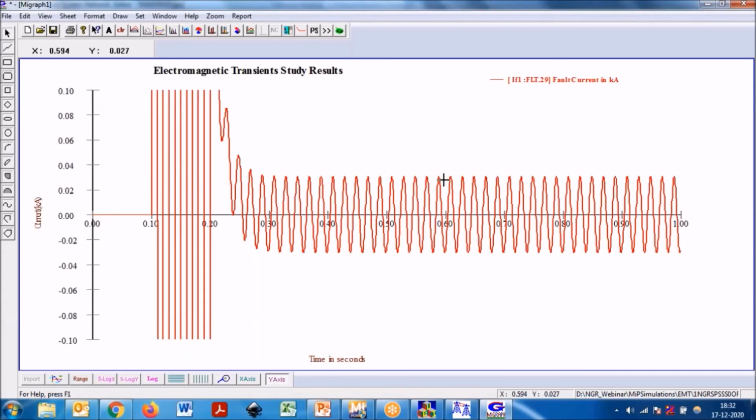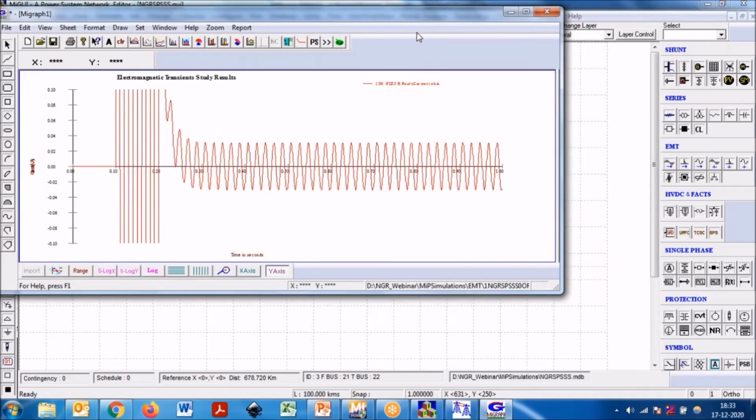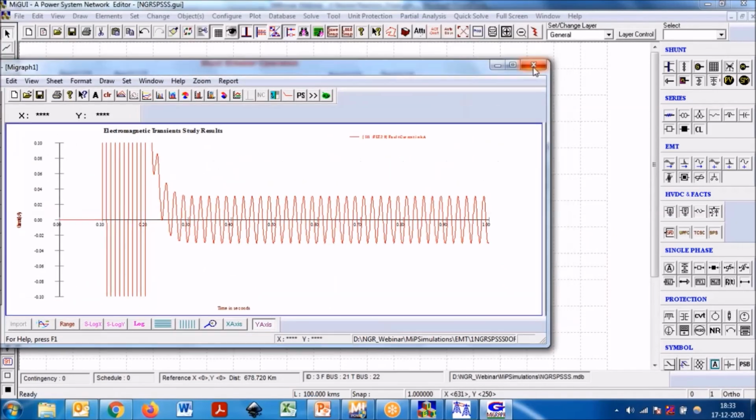Okay, so this is what secondary arc current will be, a small value in the range of around 40 amperes like this. Okay, so you have to measure the secondary arc current and RRV to get the initial value in steady state, where you can take from here.